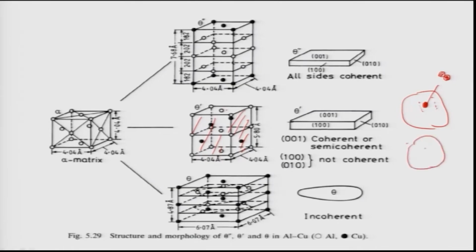around it when the dislocation moves. It can form a loop around it when it passes through. Obviously, the dislocation will come like this and then slowly bend, and once it bends it can basically form a loop like this. So, finally, it will leave behind a loop. Let me tell you. So, this is the precipitate, and the dislocation comes close to the precipitate, then it bends and finally loops around it, leaves behind a loop, and then it moves ahead.